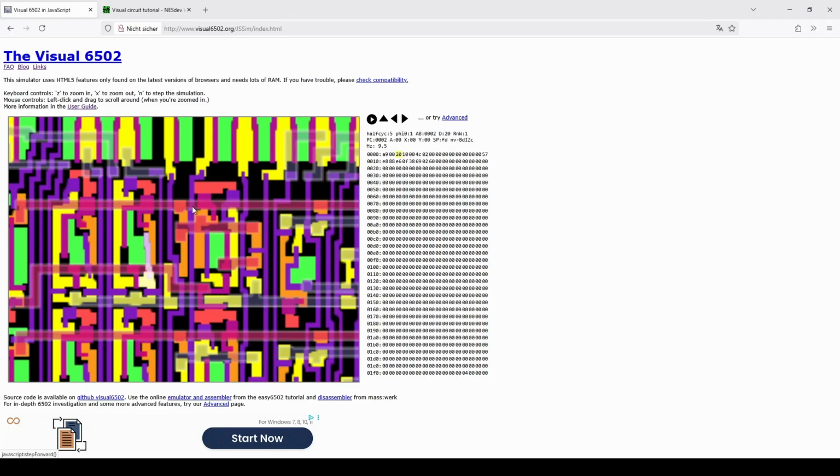So let's investigate this. It will constantly reselect. Well, then let me select something completely different there. Or maybe the clock. That's even better. So we'll just step through this until we get to the subroutine. So as you can see, it jumps to subroutine at 0010. Remember, little endian notation.